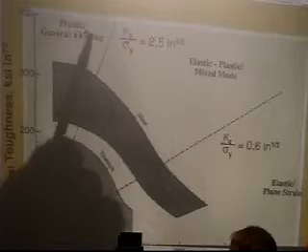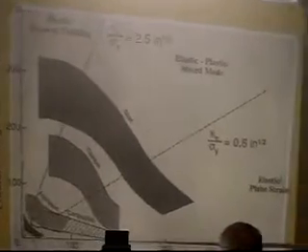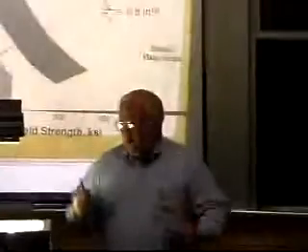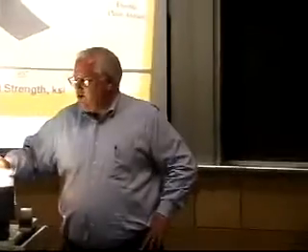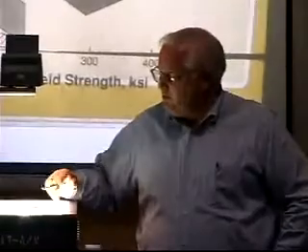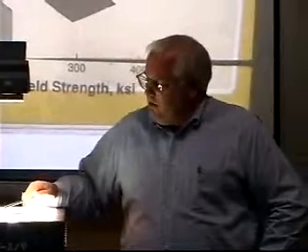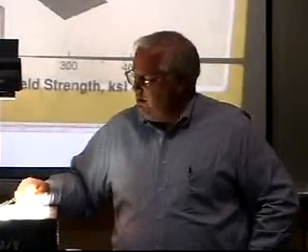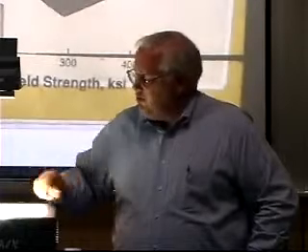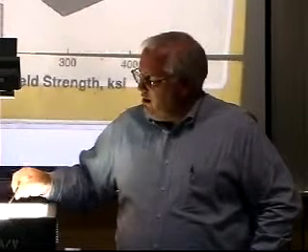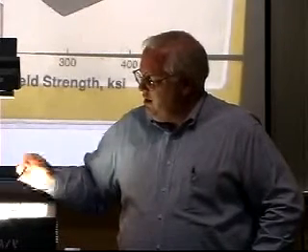You'd like to have everything pure plastic, high toughness, and plastic general yielding, but to get that, you're really paying quite a bit of money for some of these things. In general, we have something that deforms, and it's not too brittle. It's what we call elastic plastic mixed mode. And steel can do it at very high strength and very high toughness.